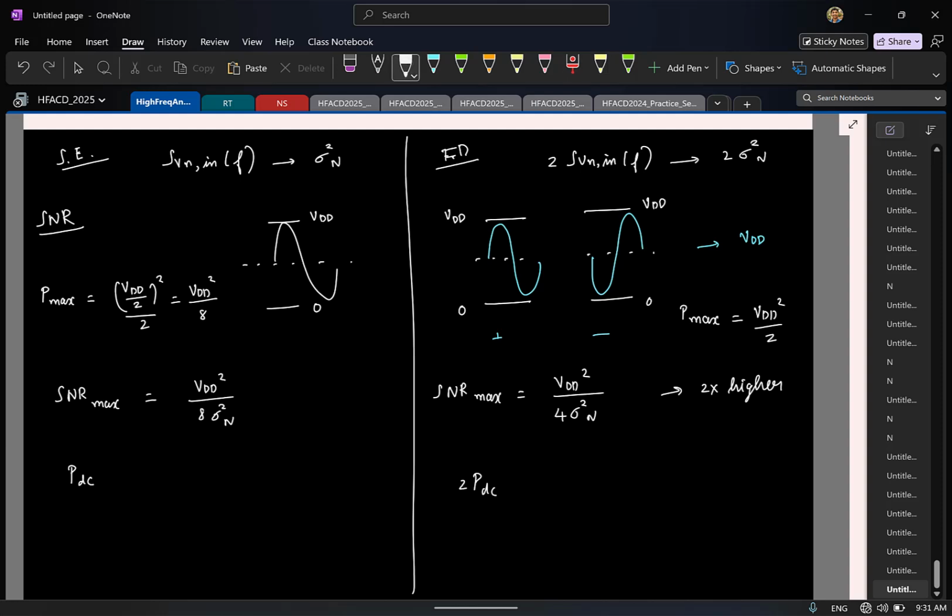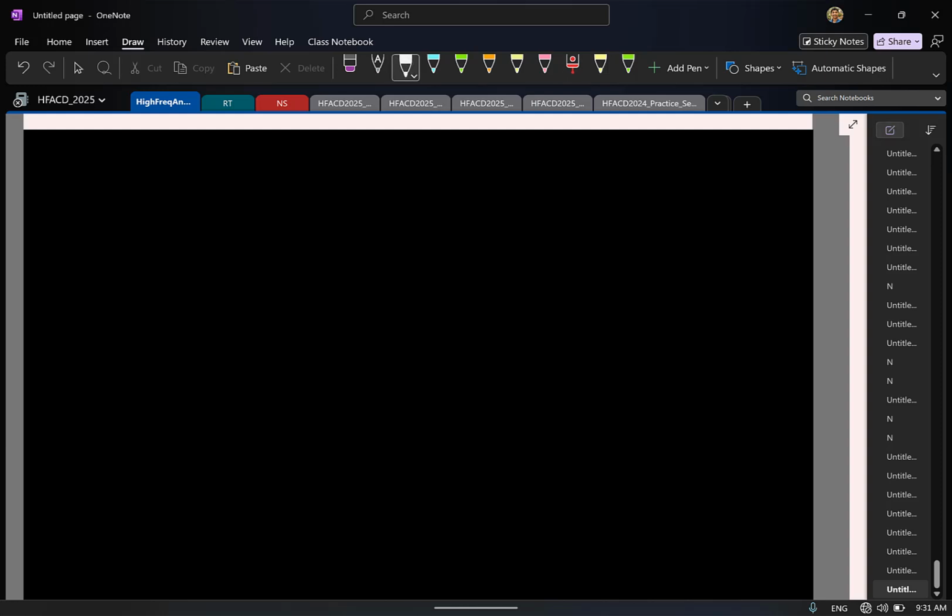So what that means is this. Let us say you have some circuit. This can be single-ended, fully differential, doesn't matter. Let us say this is realizing a transfer function H of s, having some internal nodes like this. I just marked 4 nodes for example. And let's say the noise power here is some sigma square n. Now let us say you want to maintain the same transfer function, but just reduce the noise in the circuit by 2x. It turns out one brute force way is this.